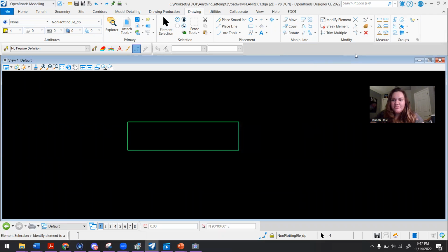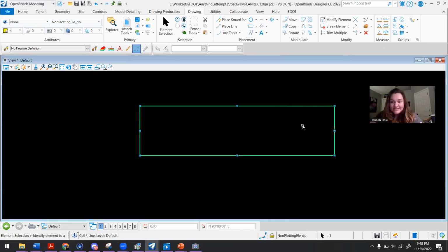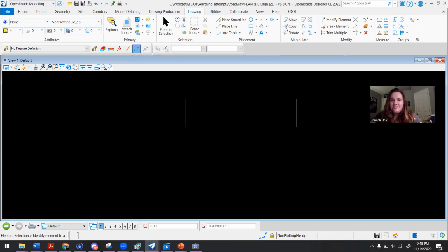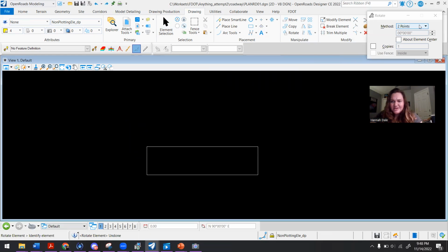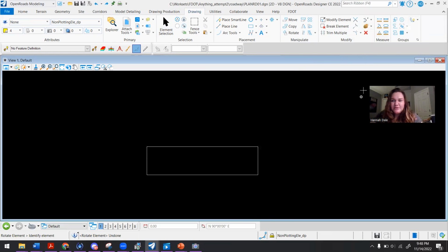So in order to do so, we are going to group elements. You can either group your elements by pressing Control plus G, or you can go over here and press group. So basically, instead of recognizing this shape as 4 individual lines, it's recognizing it as one whole rectangle. And from there, you can just rotate directly. You don't have to worry about selecting all of the elements at once. You can just go ahead and do it.